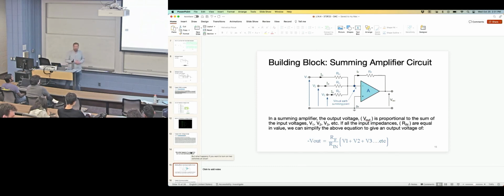Fantastic. Okay, so one trick you could do is you could have binary values represented V1, V2, V3 going through a resistor that turns it into a current. Now I have a current being pressed into this summing amplifier. The summing amplifier is going to sum these currents and give you a proportional voltage. Now, if you have different amounts of current, say R1, R2, and R3 are different values, now you can create basically a binary table of different values of currents that will sum together, producing a voltage. So let's see what that looks like.